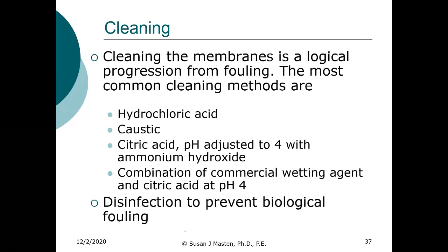And then finally, I mentioned cleaning. Fouling will occur. It's almost inevitable. And so once the fouling occurs, you need to clean the membrane, and that is typically done with acids or bases, or in some cases, a combination of both. And then you also may, again, disinfect to prevent biological fouling.